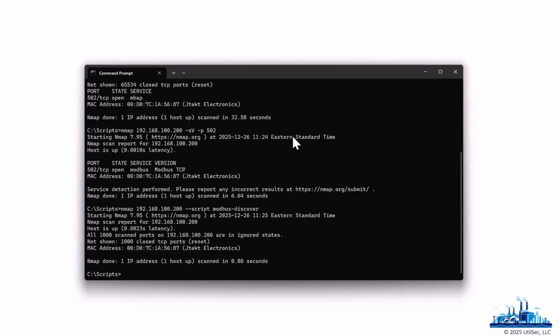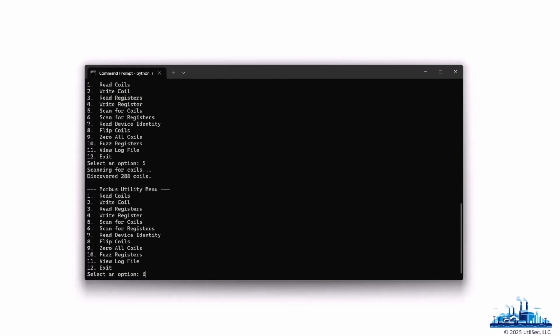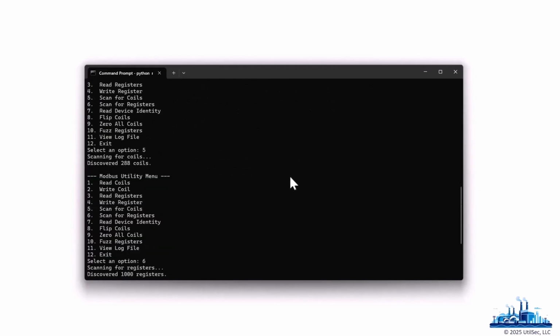So I guess unfortunately from the pen tester or attacker perspective, but fortunately from a cybersecurity perspective, even though, okay, we know, yes, there's a Modbus PLC sitting there and that we can connect to it using the Swiss Army knife. Because we can go ahead, let's type in the IP address, and then boom, you can see where we can connect. And then we can say, oh, okay, tell me how many coils and how many registers are on the PLC to start with.